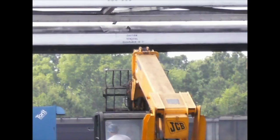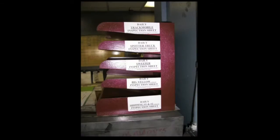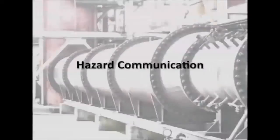Pay attention to overhead piping, power lines, and other obstructions. If you have to drive into the process area, you must use a leading and trailing spotter. And, per OSHA standards, each powered industrial truck unit must be inspected at the beginning of any shift in which it will be used. Documentation is required.